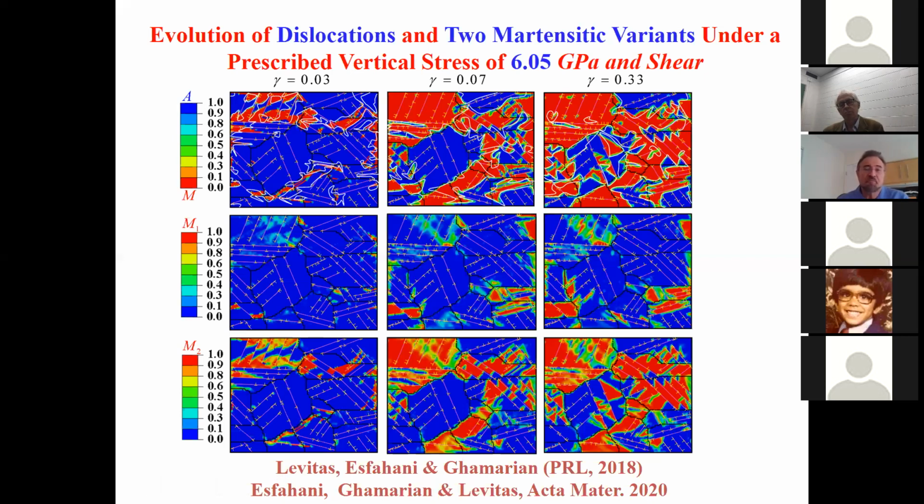Generally, yes. The problem is that nickel titanium has zero volumetric transformation strain. That is why it's almost pointless to study it under hydrostatic pressure. But yes, the same method was applied. Actually, steel is more than binary. I don't remember exactly, but it has 4 or 5 elements. So there are no limitations.